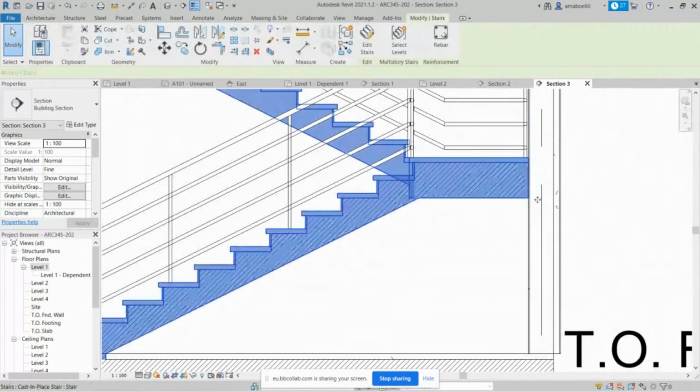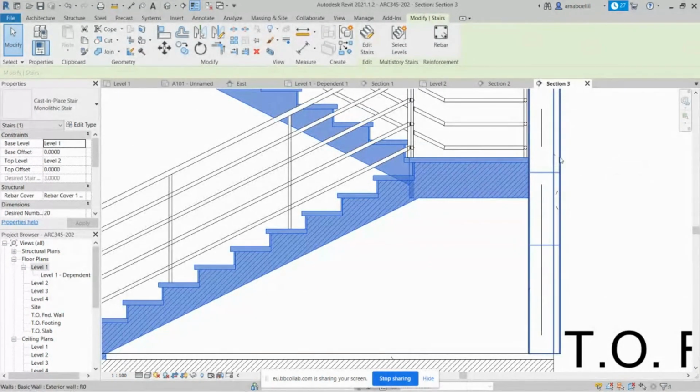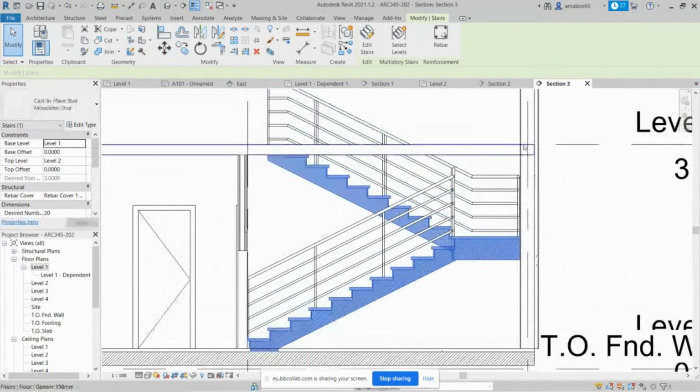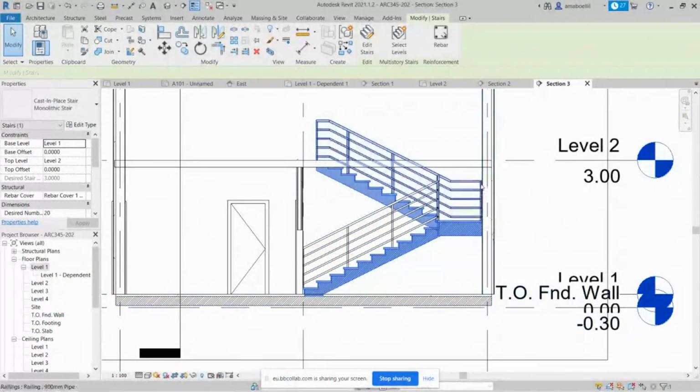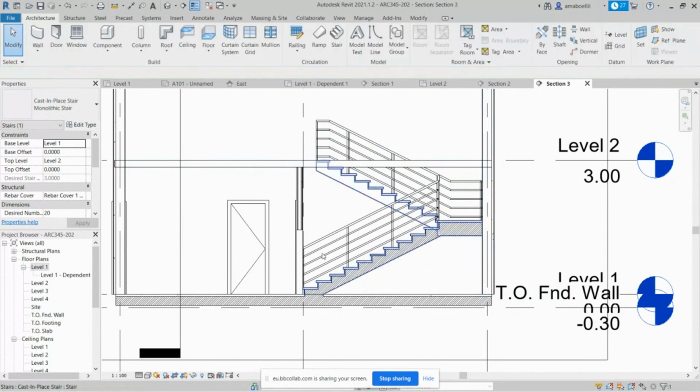And of course the stairs from here will have a beam that is holding it. And this beam, by the way, is not going to be at the same level as the floors, because you will have a beam on the ground level, you have a beam on this first level, but you don't have a beam in here. So that's why you create a beam to host this landing that is in between the two floors. Okay, what else do we want to discuss?